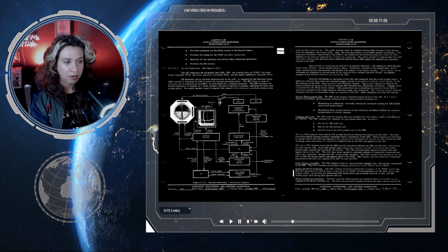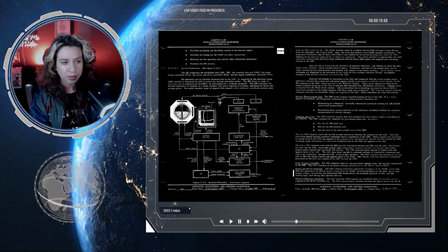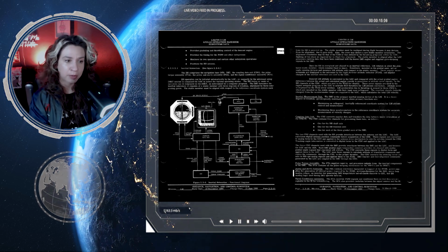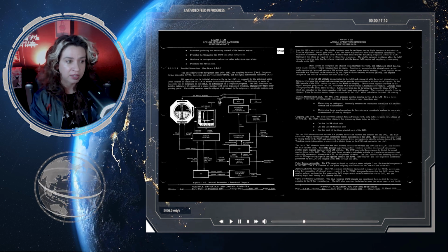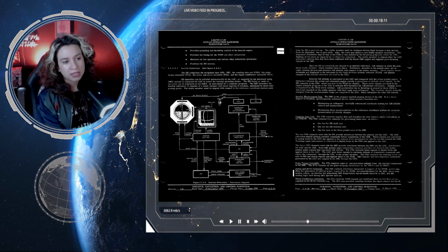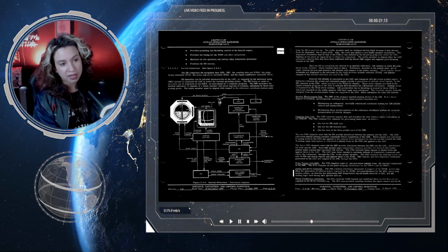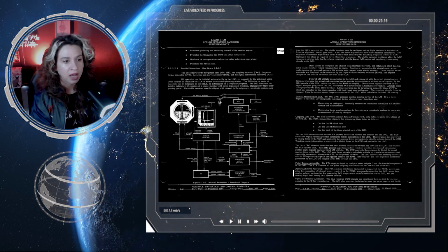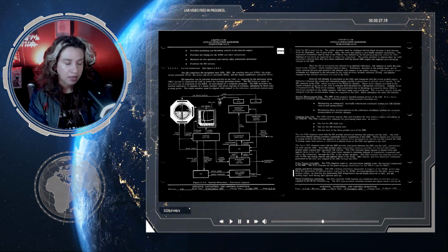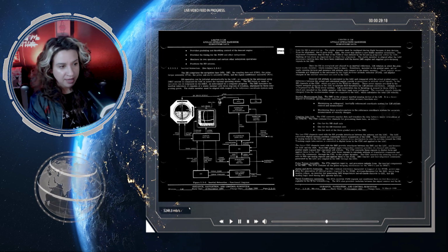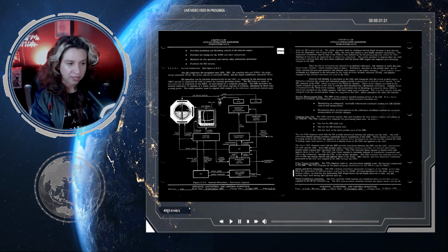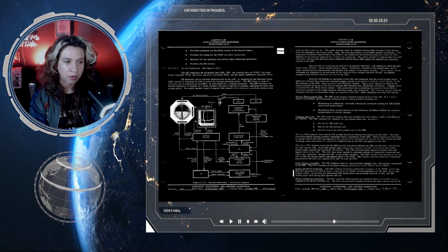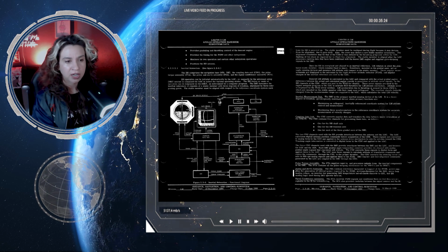The PTA, or the Pulse Torque Assembly, supplies input to and processes outputs from the inertial components in the IMU. The PTA contains all pulse torquing electronics for the PIPAs and for the IRIGs. The PSA, or the Power and Servo Assembly, contains electronic equipment in support of the PGNS.